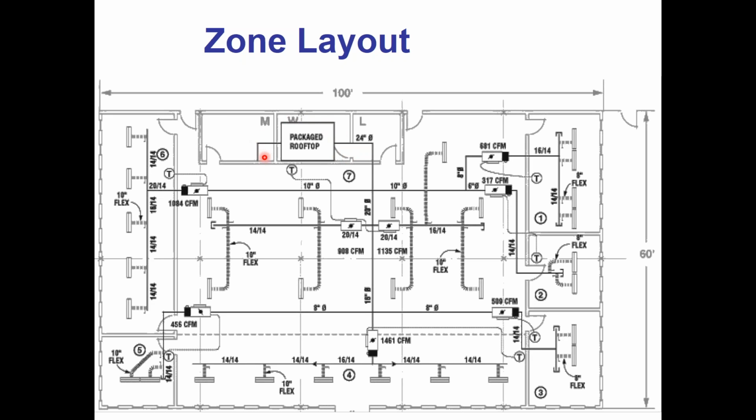Because if I was to allow this guy to go into heating mode, because maybe these guys over here in the morning need some heat or whatever, how are the guys in the middle going to get their cooling now? There's 100-degree air in the duct. How am I getting cooling for these guys in the middle that need cooling year-round all the time, no matter what? Because an interior zone needs cooling on a 0-degree day.